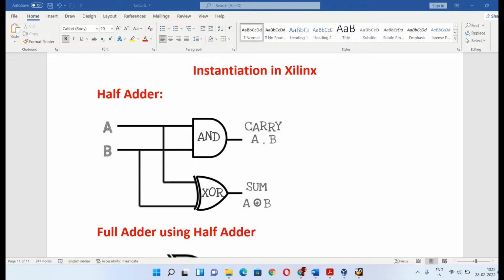A module provides a template from which you can create actual objects. When this module is invoked, it creates a unit object from the template, and each object has its own name, variables, parameters, and input output interface. The process of creating objects from a module template is called instantiation, and the objects are called instances.